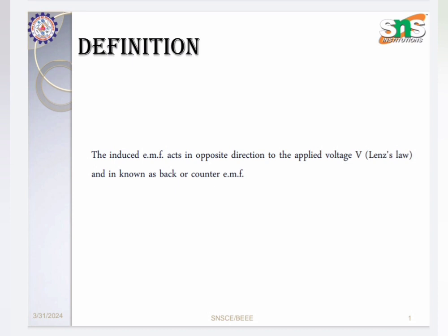As the motor turns faster and faster, the back EMF grows, always opposing the driving EMF and reduces the voltage across the coil and the amount of current it draws. This effect is noticeable in a number of situations.